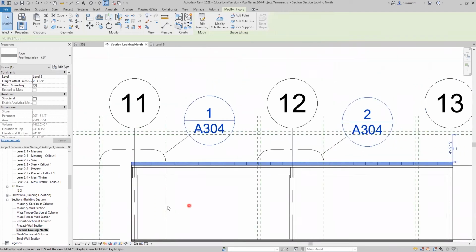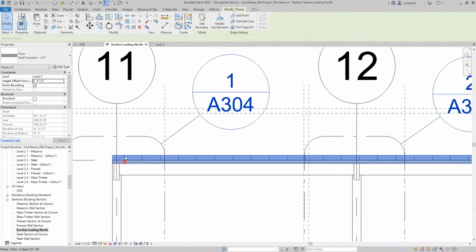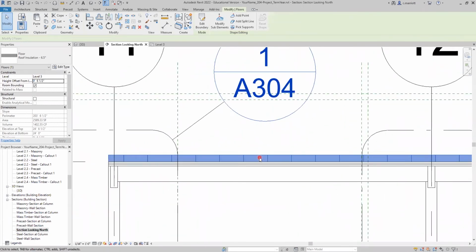Okay. So here we have this very thick assembly of insulation. It's going to taper down to where drains will be located. And based on our study of R values, we're going to make the insulation 4 inches thick at those drain locations, and then it will taper up. So some areas of the roof will actually have a higher R value than others.